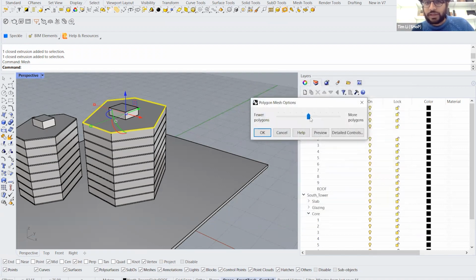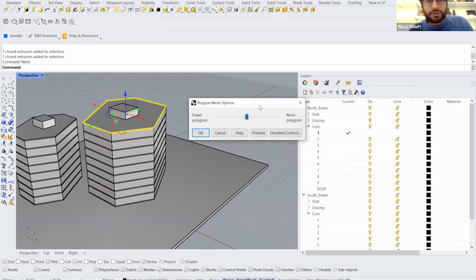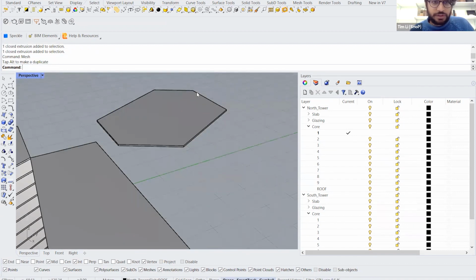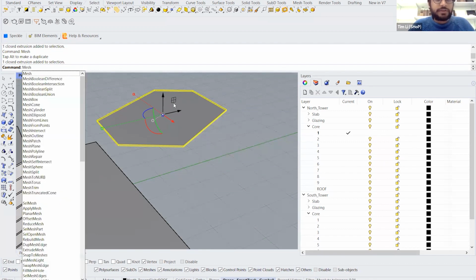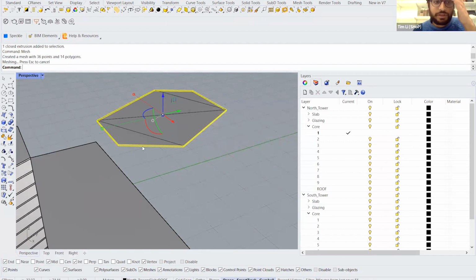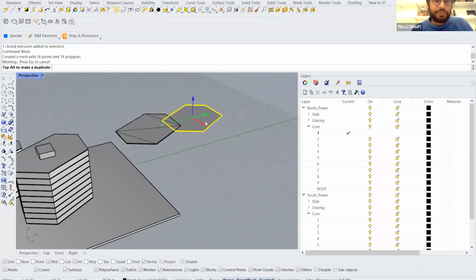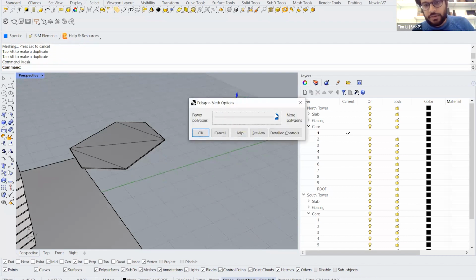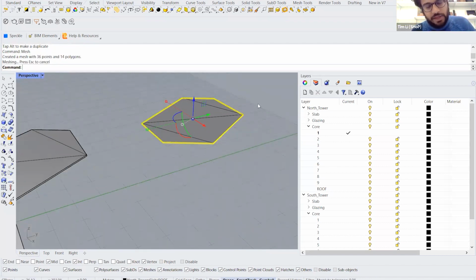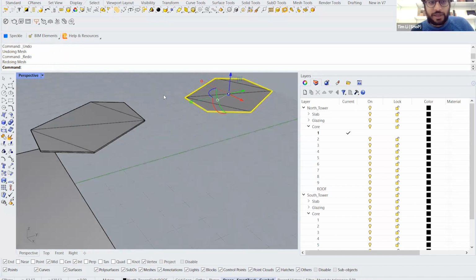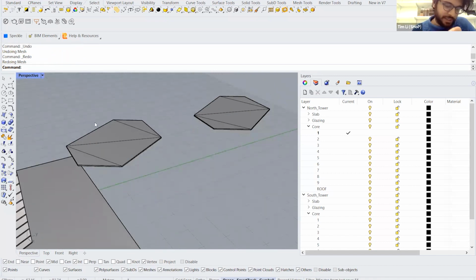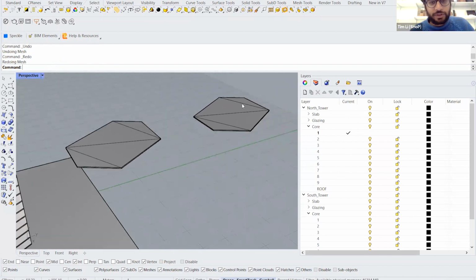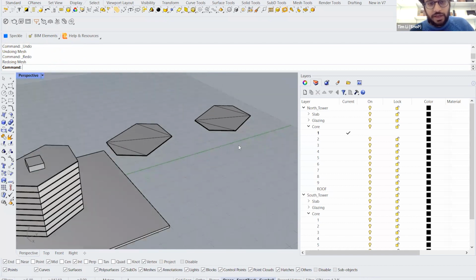Okay. So basically when you go to export, it'll give you this dialog, which I'm sure if you guys have used Rhino, you've probably seen, but let's see if I can do a quick demo. For example, if I take this NURB surface and make it into a mesh on the fewest polygon settings, you see it provides one type of mesh detail. If I do that again on the higher level settings, in this case, it is the same density of mesh just because this shape, like I said, is so simple, but you can imagine if this was a more complicated shape, doing a different meshing process will result in a heavier mesh.